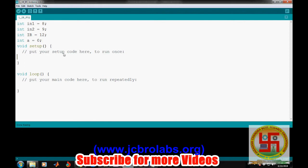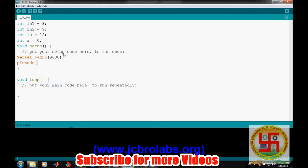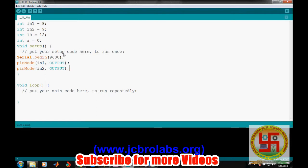Now we will also send the status of the sensor to the serial port. So let's define Serial.begin(9600), and then define the pin modes. Because the DC motor is an output device, IN1 and IN2 have been set as outputs, and for the IR sensor, we are going to read data from it, so this IR pin has to be defined as an input pin.